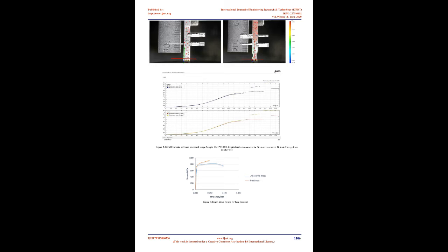To obtain a true stress-strain curve, an engineering approach is applied using another software tool, Autodesk AutoCAD. As the miniature test was carried out with an orthogonal arrangement of cameras, camera 1 gives us the width and rear camera 2 gives us the thickness of the sample. By manipulating and comparing images at selected points on the curve, the actual cross-section area for calculating stress has been obtained. A sample Figure 1 is shown below.